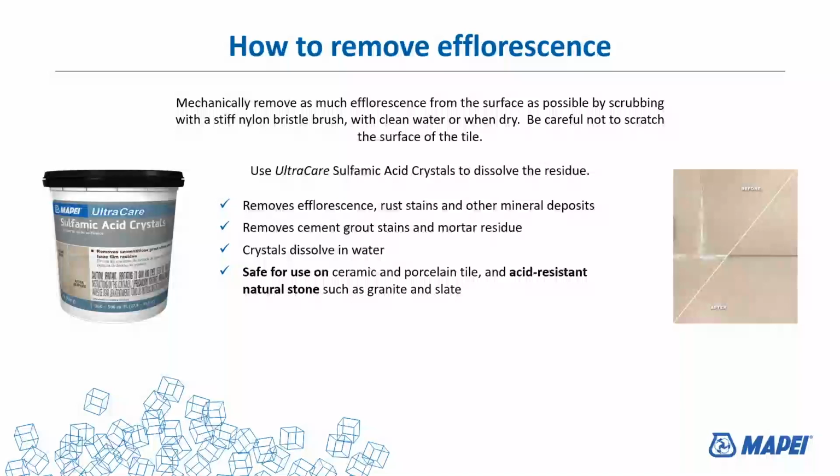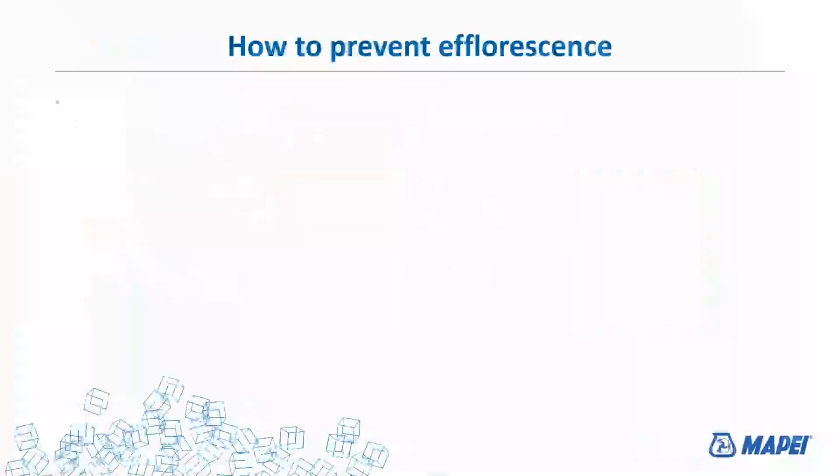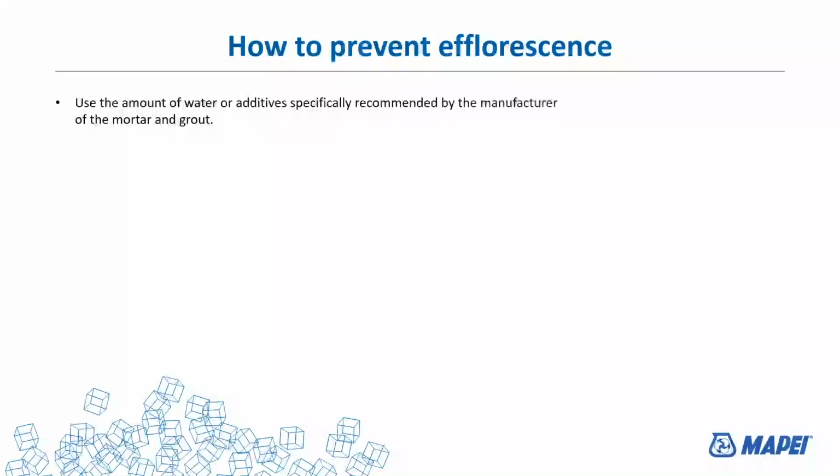$1 million question: how to prevent it? Keep it from getting wet. The amount of water or the additives specifically recommended by the manufacturer is very important. When the bag says add 5 quarts of water to 50 pounds, you add 5 quarts of water to 50 pounds, not 4, not 6, 5. And that's the importance of the measurement.